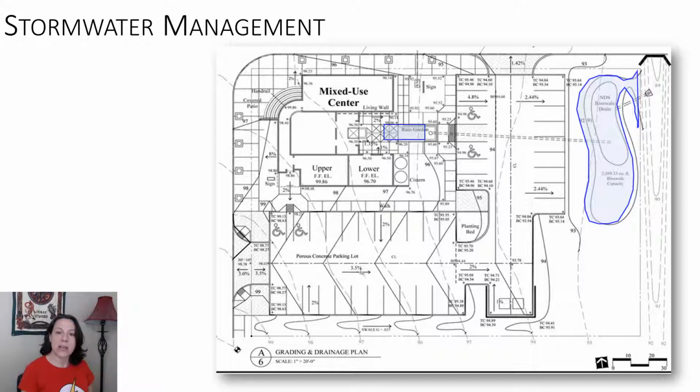You can also see here these arrows, so I have a contour here that drains and then it goes to a 97. Here's the contour here and it goes to a 98. So I know that the water's draining this direction, and they're telling me it's 3.5%. Same with here. So the site all drains back to this bioswale over here.